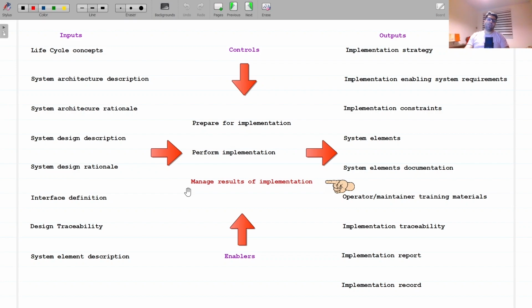Here are some of the usual common approaches and tips. Keep the Integrated Product Development Team, or IPDT, engaged to assist with configuration issues and redesign. Inspections are a proactive way to build in quality. In anticipation of improving process control, reducing production inspections, and lowering maintenance activities, many manufacturing firms use Design for Six Sigma or lean manufacturing. Conduct hardware confirmation audits or system element level hardware verification.